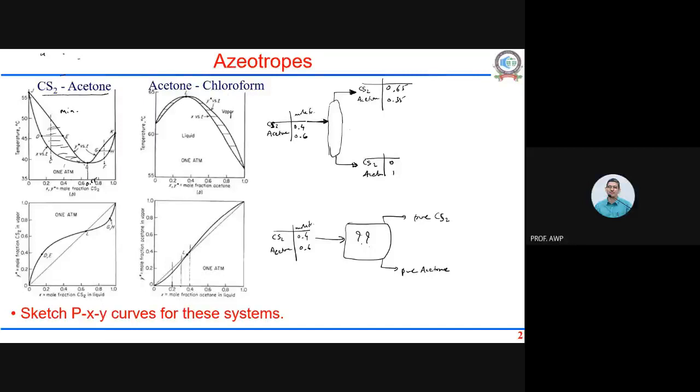How do you decrease the pressure, and how will the azeotropic point be removed, or how will the composition change, or what do you want to do? So we can go for vacuum distillation. But how will the azeotrope change? So you want vacuum distillation here itself, or another column?